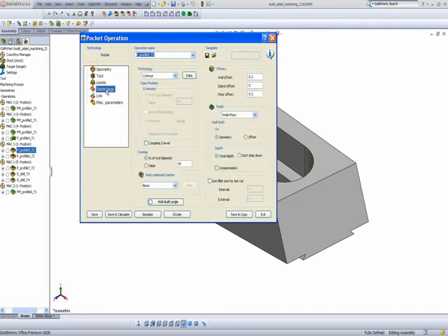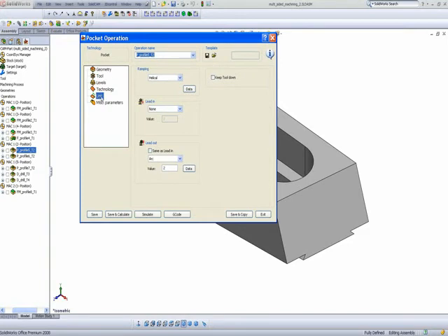And in my technology area, I'll be using wall offset plus a floor offset, and I'll also be doing a finish cut. In my link area, I'll be going straight into my part using a helical motion, as seen here. And I will lead out with an arc.